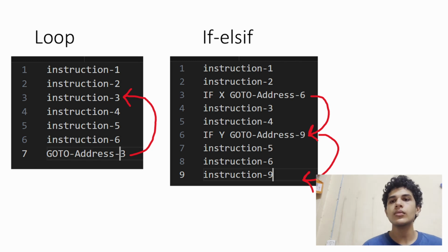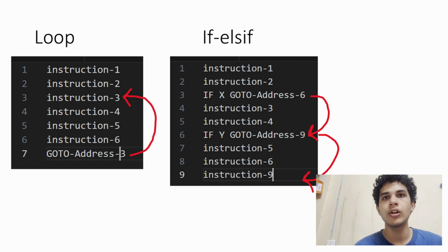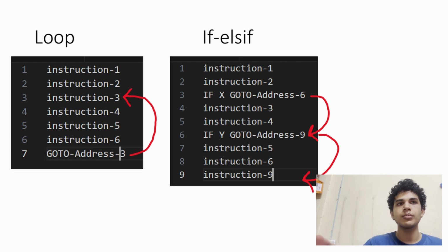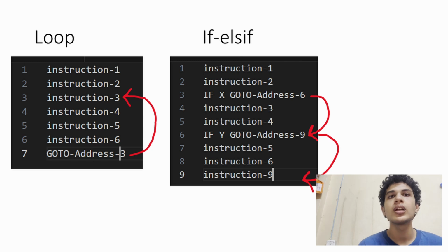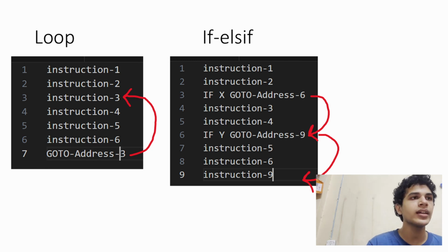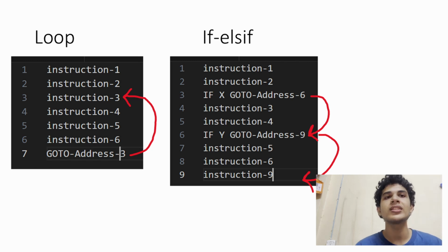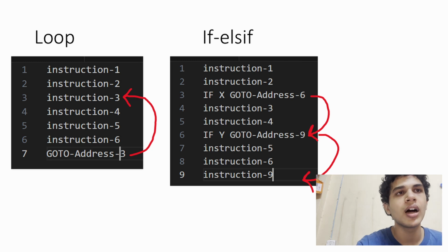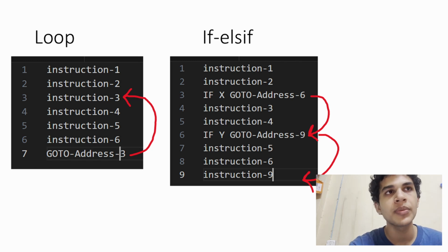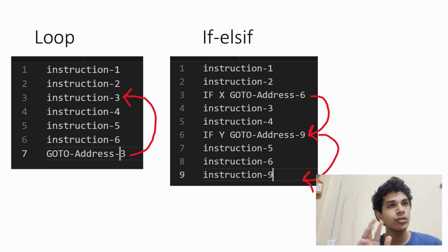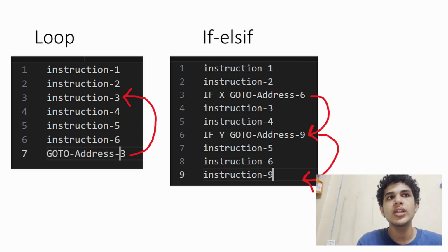Now this is a very elegant process, and it works for all code that has to be run sequentially, as in there is a single process to follow, and there is no branching, there is no looping. However, in the case of branching and looping, just going to the next instruction doesn't necessarily work. Now to handle that, 2 separate new instructions are created, and the way they essentially work is that rather than going to the next address by default, if the instruction go to is run, it goes to a specific address, and the way it's generally defined is go to the next address minus some shift.